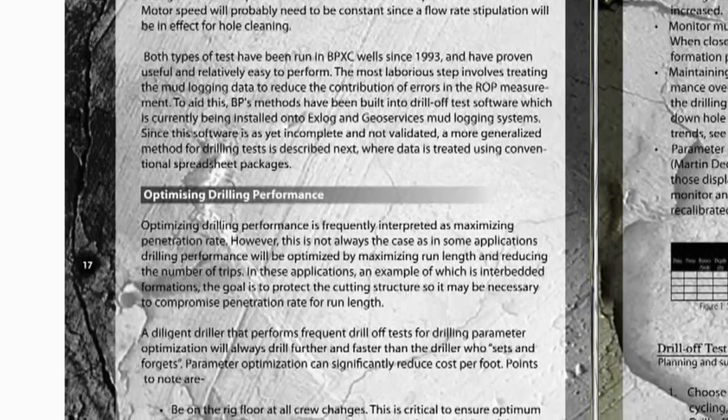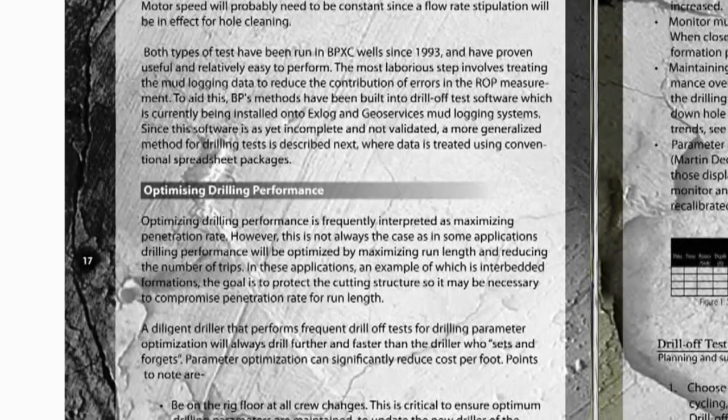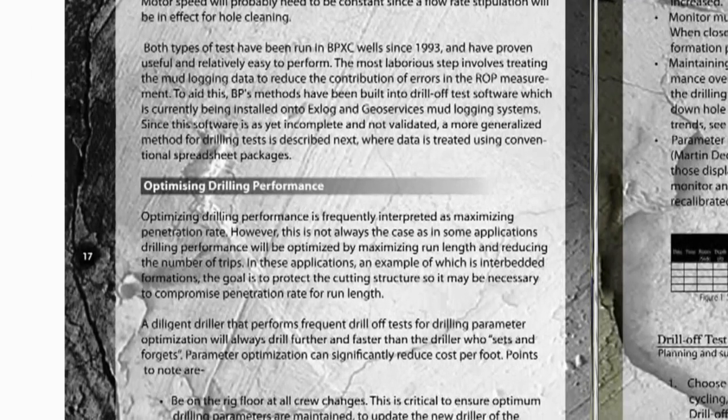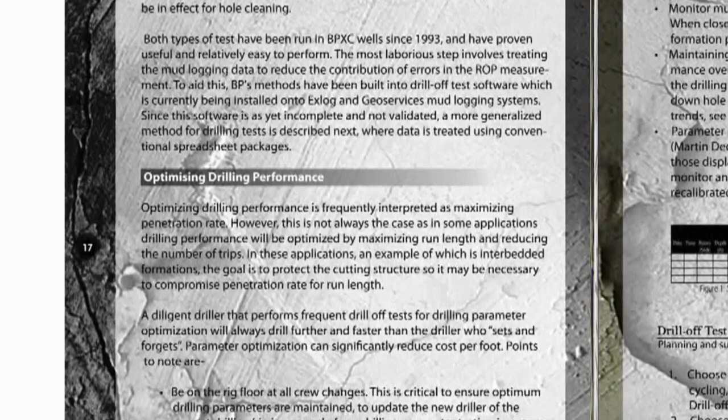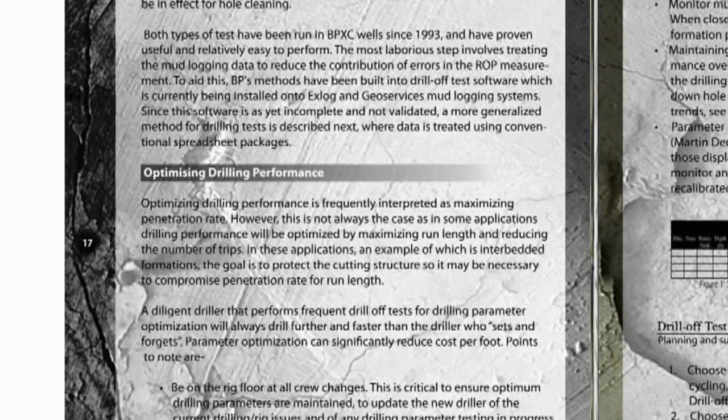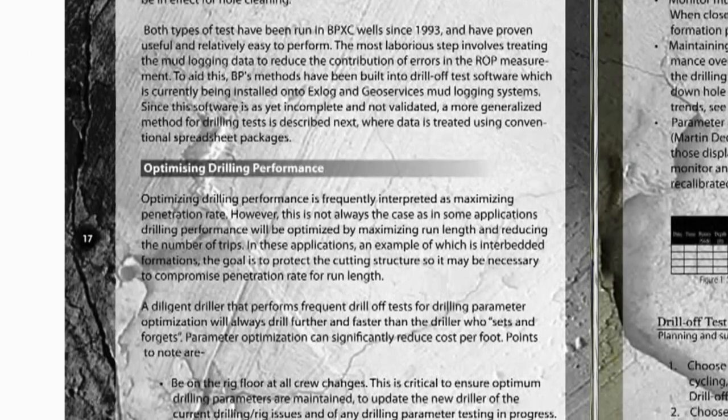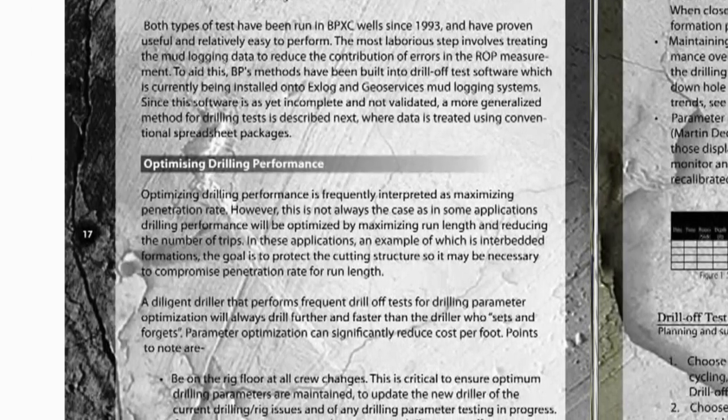Optimizing drilling performance. Optimizing drilling performance is frequently interpreted as maximizing penetration rate. However, this is not always the case, as in some applications, drilling performance will be optimized by maximizing run length and reducing the number of trips.